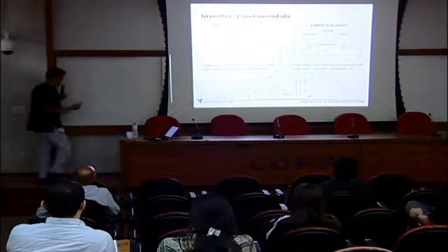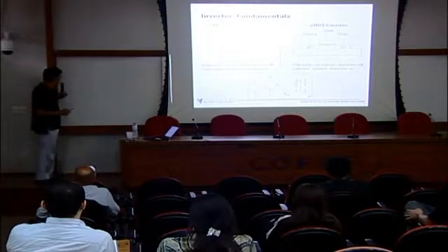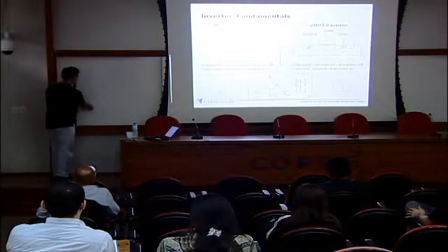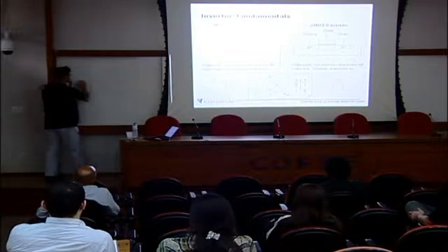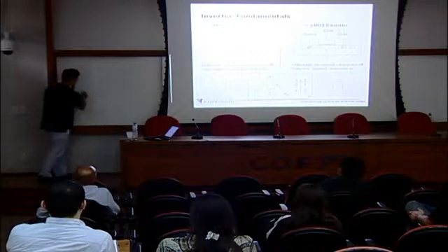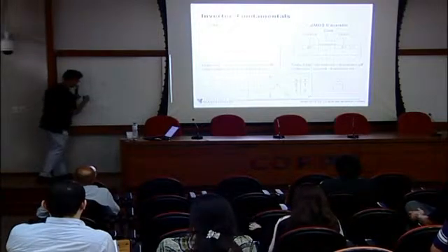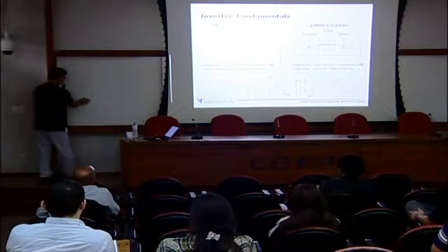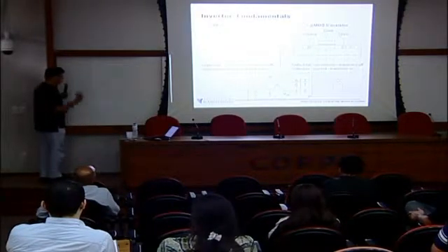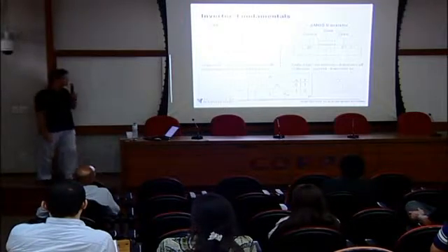And on the other way, if we make the input of the gate as 1, then this one is turned off, and then this one is turned on. Then this one is directly connected to 0. Then that means the output Y is 0. Okay. So this is the inverter. 0 is input, and then output is 1. So it's reversed, right? And then 1 becomes a 0.